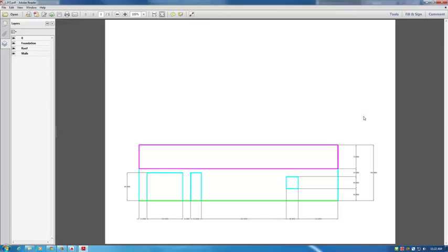So if you want to send somebody a drawing via email and you know they don't have AutoCAD at home or whatever, export it to a PDF and send it to them. You've got the same drawing and anybody can open it up. All Windows computers come with a PDF reader. So that's another handy extension that you use for emailing or sending files to somebody else that does not have CAD software on their computer. So that's the basics of saving as different file types.